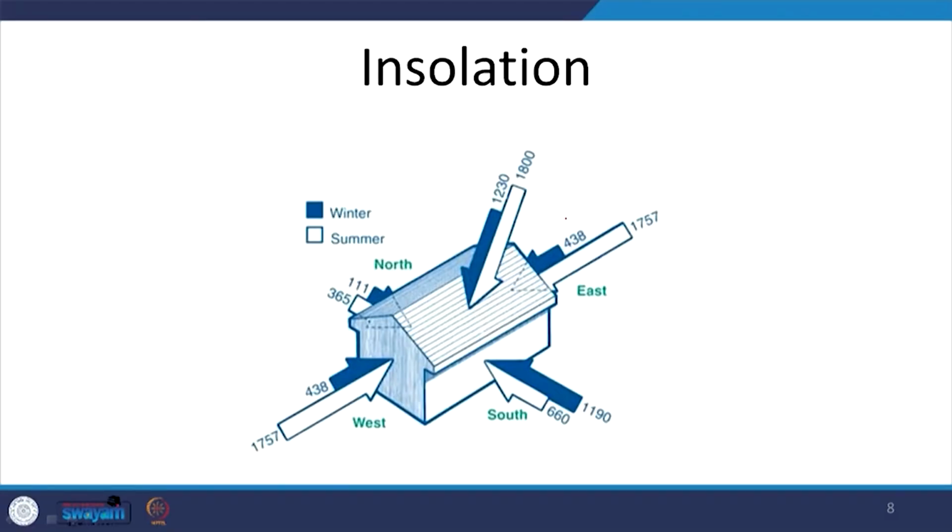Now, that is done because all these surfaces are exposed to the solar radiation. So, we have to reduce the amount of insolation received during summer, but we also have to see the amount of solar radiation which is received during winters, because the building, especially in composite climates, may require heating in winters, and if we look at the total energy budget, sometimes the cost of heating and the energy required for heating the building may surpass the amount of energy required for cooling the building